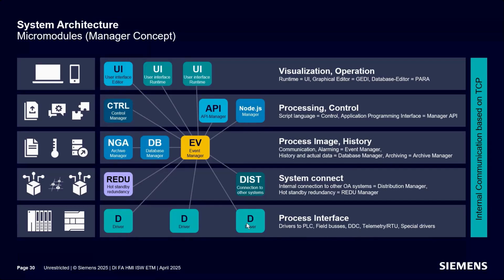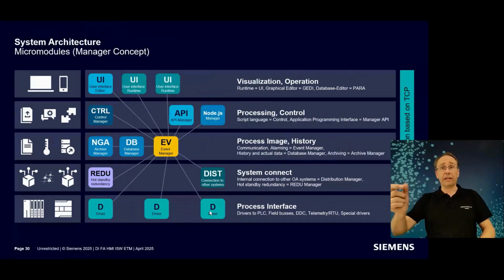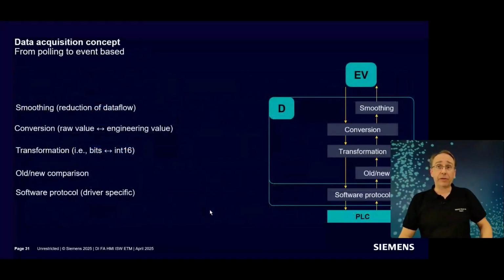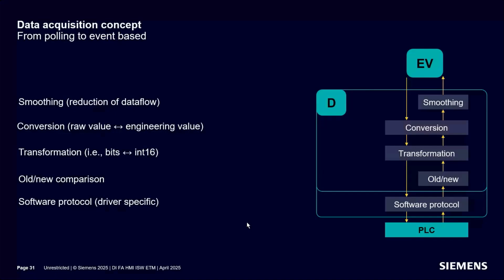For example, with OPC UA, you can subscribe, then you can tell the server to only give you the information when there is a change of data of more than 0.5% or something like this. The SIMATIC driver can also do that and many more. But some cannot. For example, with Modbus, you need to poll. But that is now the important thing: this can be done by any driver, this Modbus was just an example.